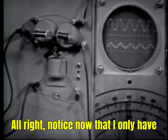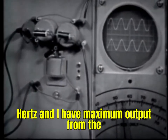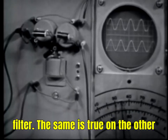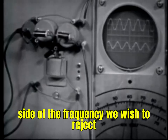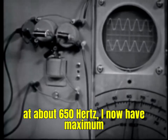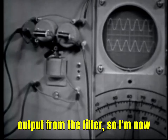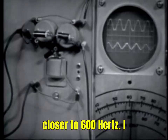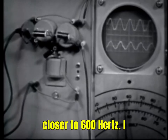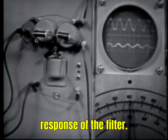All right. Notice now that I only have to go down to about 550 hertz, and I have maximum output from the filter. The same is true on the other side of the frequency we wish to reject. At about 650 hertz, I now have maximum output from the filter. So I'm now rejecting a band of frequencies much closer to 600 hertz. I have indeed improved the frequency response of the filter.